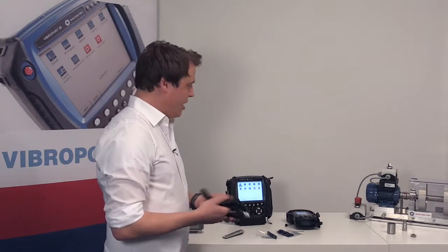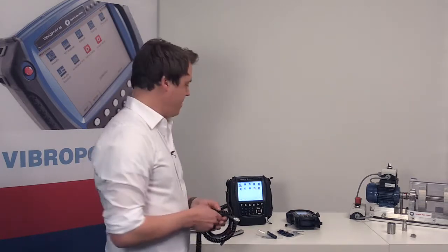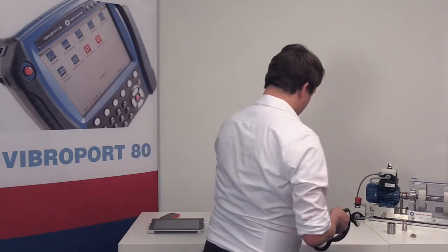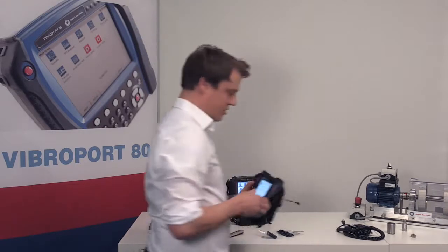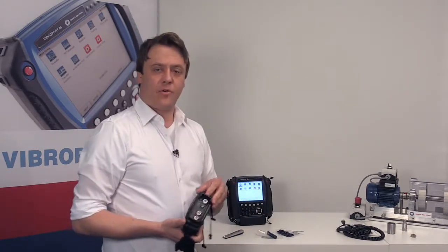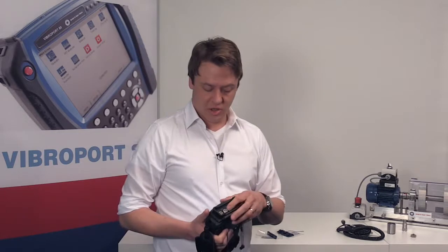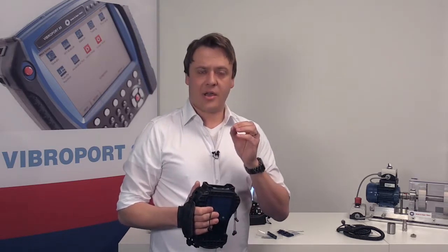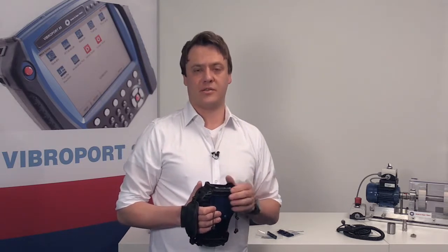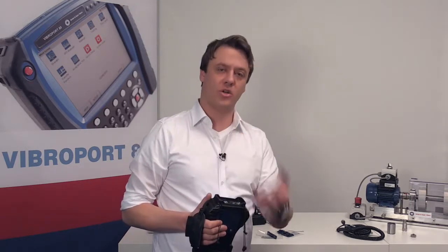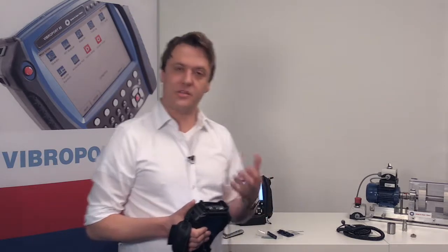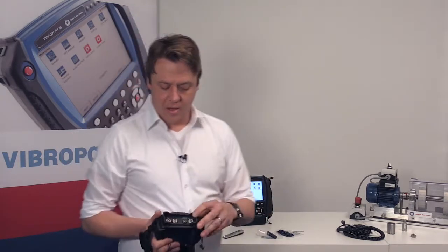Okay, so now let's build up the measuring chain. This is very easy. Let's explain it on the VIBROTEST 80, the small instrument. You have 4 connector sockets: channel 1, channel 2, channel R, and trigger channel. There is a distinct rule how you have to connect the sensors. There's only one way if you go from 1 channel measurement up to 4 channel measurement. And this way I would like to explain for you.